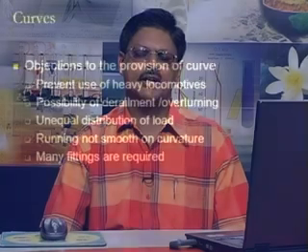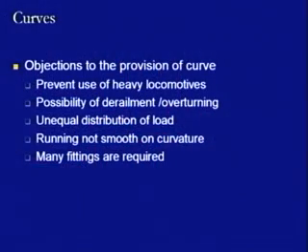And further, when we have curved tracks, more fittings are required because of the effect of centrifugal force, due to which these rail sections may go out of alignment or go out of gauge. So as to make them remain in position, more fittings are needed or provided.